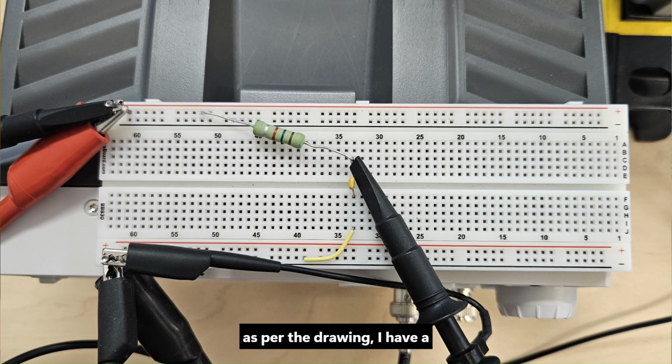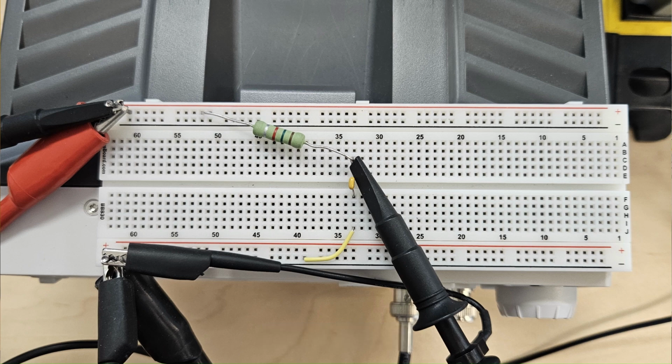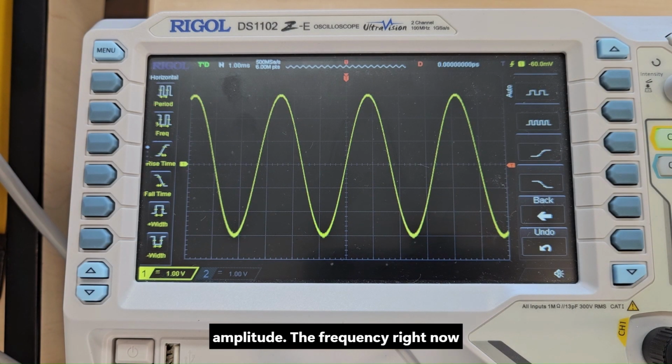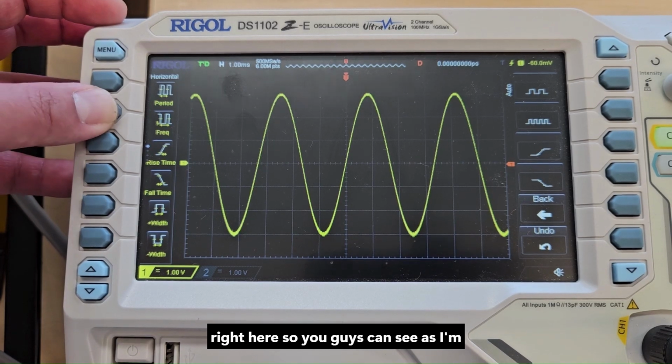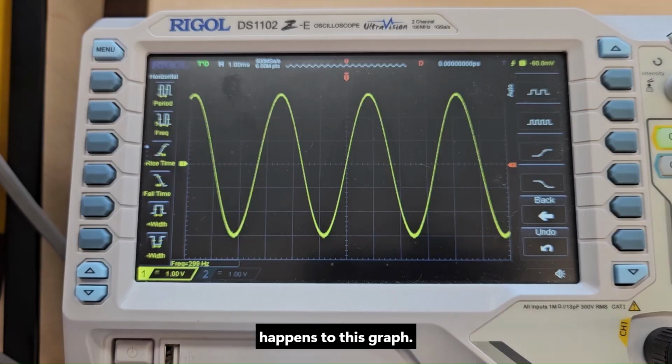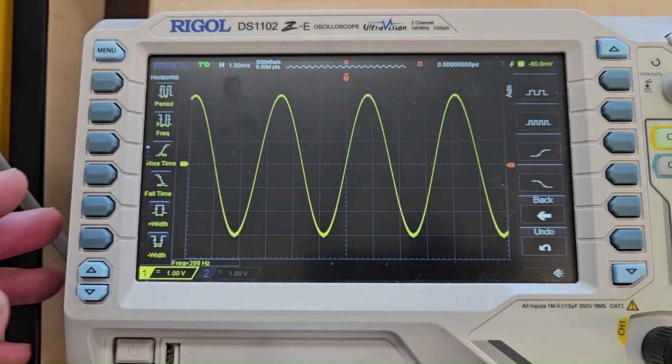So as per the drawing, I have a 1500 ohm resistor and a 220 nanofarad capacitor with a 6 volts peak to peak of amplitude. The frequency right now is 300, and I'm going to set that up right here so you guys can see. As I'm altering the frequency, we'll see what happens to this graph.